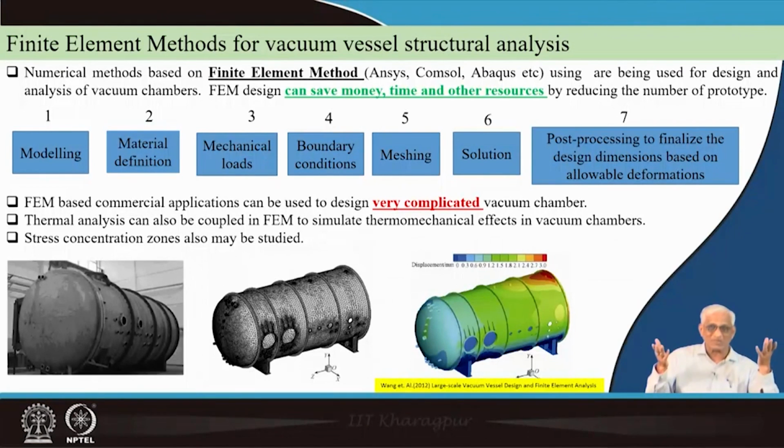Nowadays, we don't have to explain this to engineering students because it is a magic box. The powerful software will take care. All that we need to do is mesh the surfaces. That is where the beauty lies, how best you can do. And in very complicated areas, there are crucial areas, you have to decrease the mesh size so that the accuracy of your calculation will be more and more.